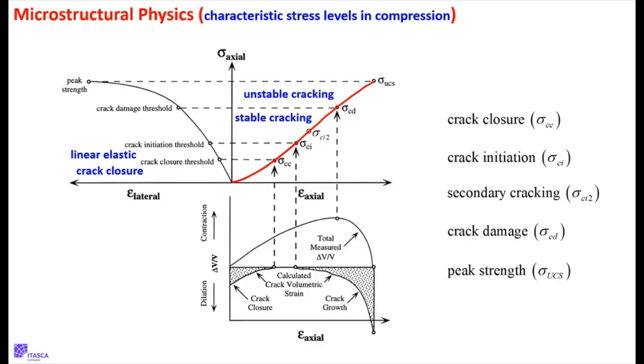So you can work out an expression for an elastic body. But we don't need to work out the expression. We know theoretically how to measure volumetric strain, and we can get it if we know the lateral strain and the axial strain. So then this curve here is what you get.